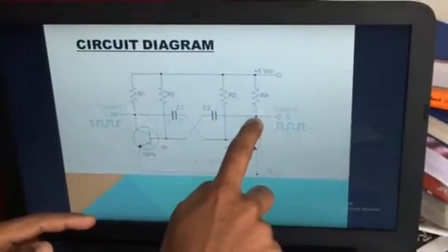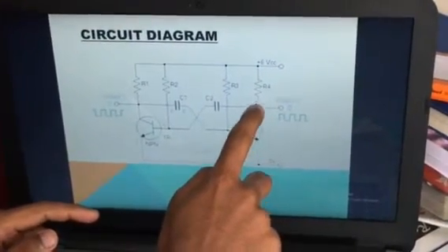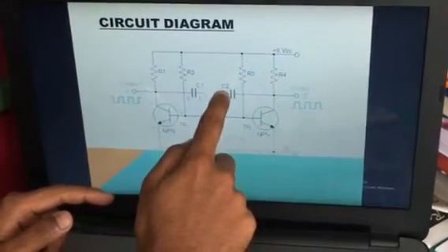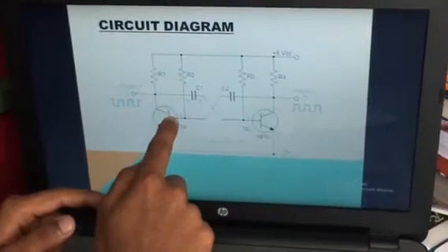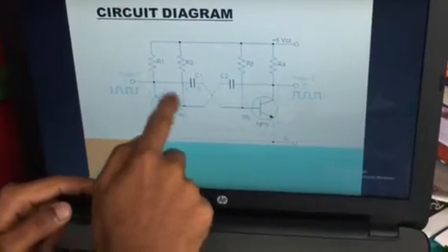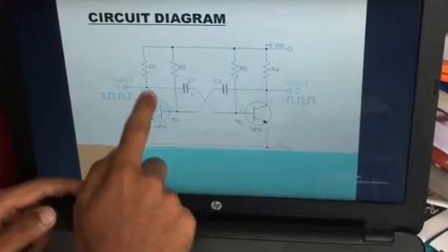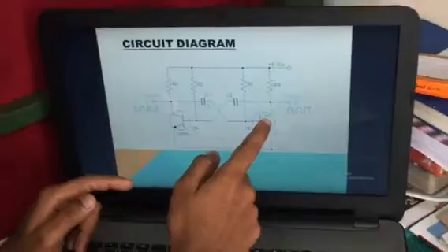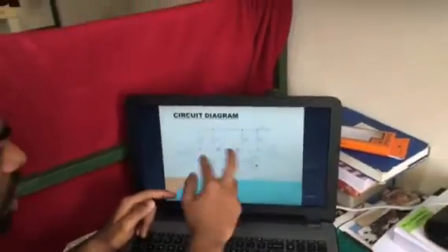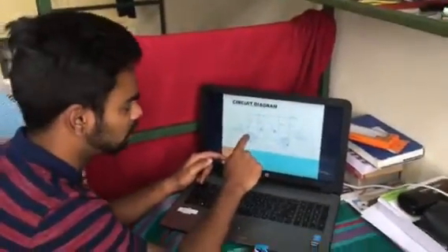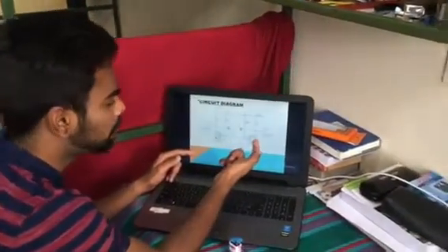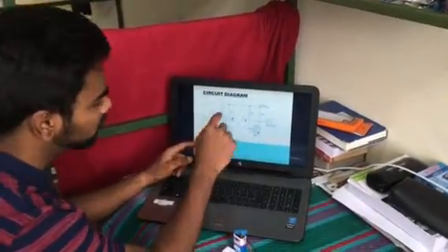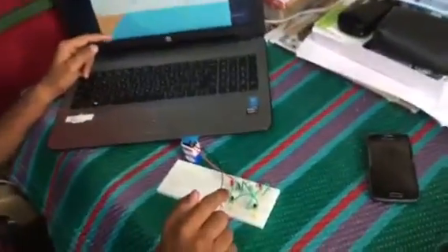So at this point we get a high voltage. And when this high voltage is given to the base, it comes through this way. This again goes to the saturation region, and the other again goes to the cutoff region. So it changes its state. It goes to saturation, it goes to the cutoff region. So one conducts, one does not conduct. So this is how we get an output in this mini project.